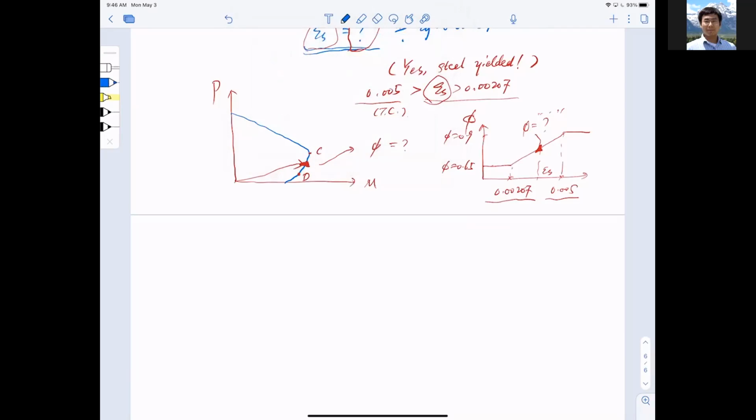Why is that? It's because Pn equals Cc plus Cs minus Ts. Now you don't have to worry about the sign because tension is indeed tension, right? And how about Mn? Mn equals Cc times half H minus half a, remember, plus and so on. We have a long equation; you can use the equation from before.